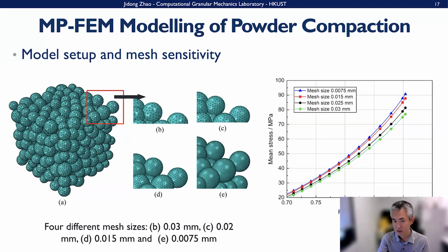So you can do a mesh sensitivity study, and this is what we call, numerically, a consistency study. And then you choose an acceptable set of mesh for your study here.